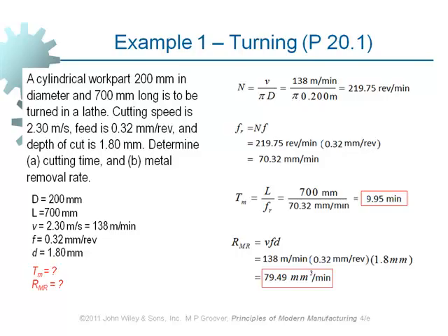However, if you are making use of a CNC machine, any cutting speed is available. Any spindle speed is available on it. On CNC machines, because it is continuous, any spindle speed is made available. On a conventional machine, it's not the same. You've got to make use of definite spindle speeds. Okay? Good to know.